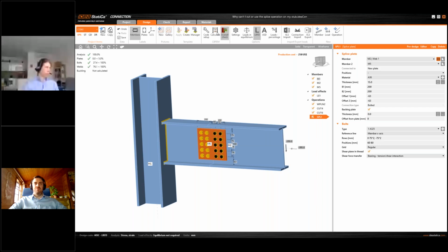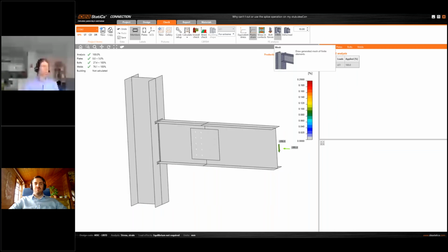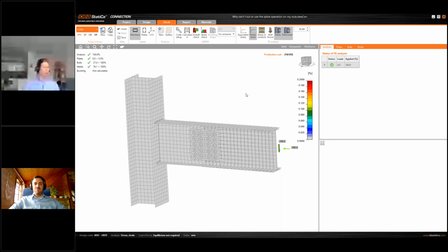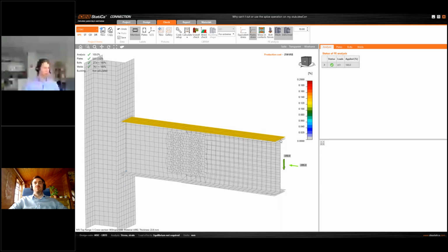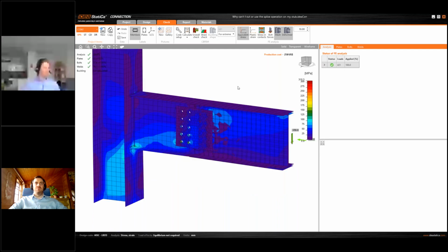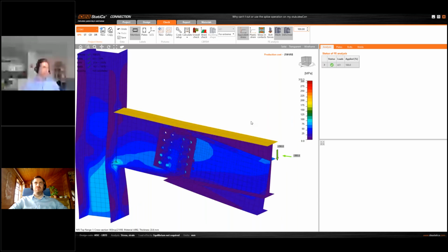What's wrong? Let's take a look. Turn on plastic strain, mesh deformed, the favorite combination of checking the outputs. And I can see something wrong is happening here. What's that? Then run the equivalent stress. I can see there are some strange spots on the mesh. Let's see if I increase the scale of deformation. I can see there is something definitely wrong, right?